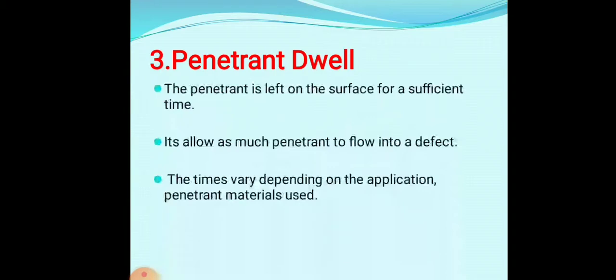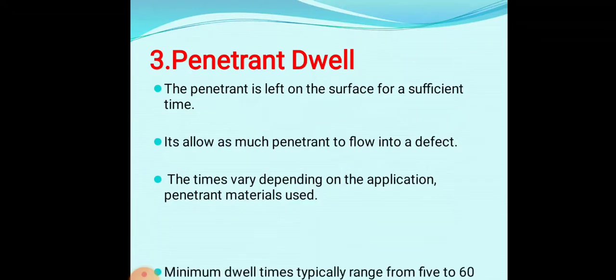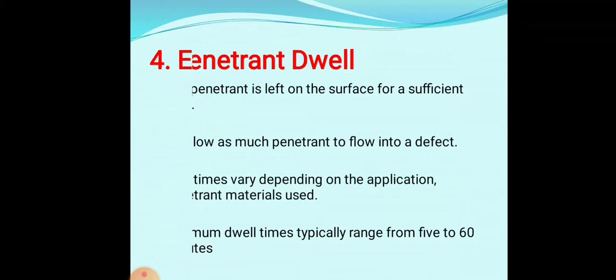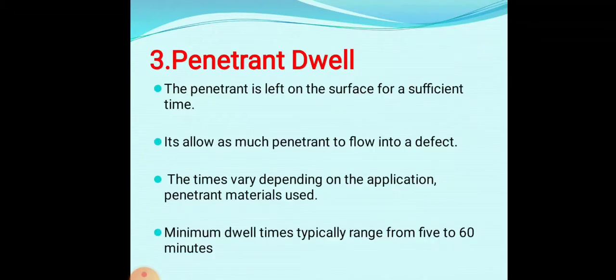The time depends on the application and the penetrant material used. The time varies depending upon the material used as well as the penetrant selection. The minimum dwell time typically ranges, on average, from 5 to 16 minutes. It will vary depending on the penetrant used or material selection.